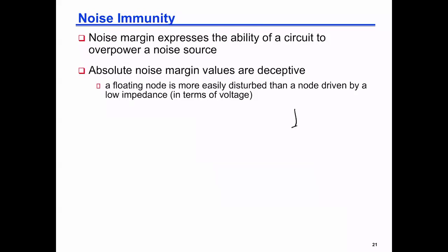Let us assume that I have a resistor connected to VDD and a capacitor here, and let us assume we inject some noise at this node. Who will help the capacitor recover from this noise? What should be the ideal voltage here at this node? At infinity, where will the resistor take the capacitor? VDD. It will charge it to VDD, right?